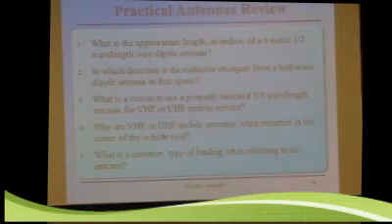Okay, what is the reason to use a properly mounted 5/8 wave antenna for UHF, VHF mobile service? It has a longer range. Yeah, there's two aspects to it. It has a lower angle of radiation, if you remember the picture we saw, and more gain than a quarter wave, and so it usually provides improved coverage. That's the official answer for that.